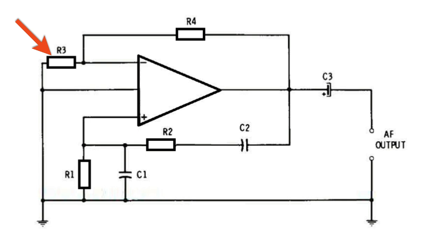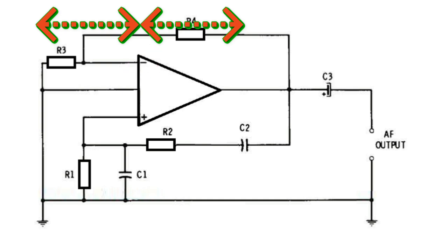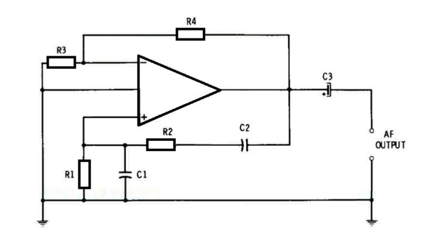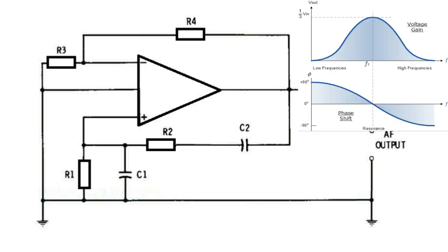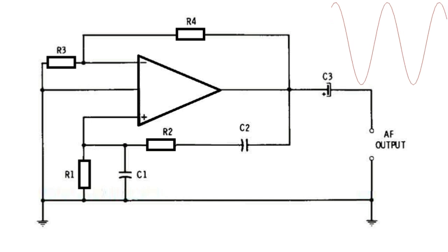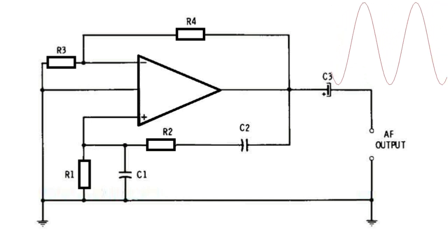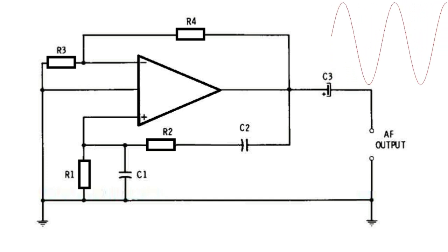The resistors R3 and R4 provide the negative feedback that works like a signal voltage divider to the inverting input terminal. This negative feedback helps to reduce the output signal distortion, but it should be implemented with the right proportion by appropriately adjusting R3 and R4. This is important to ensure that it doesn't cancel the positive feedback, leading to the elimination of the oscillation.